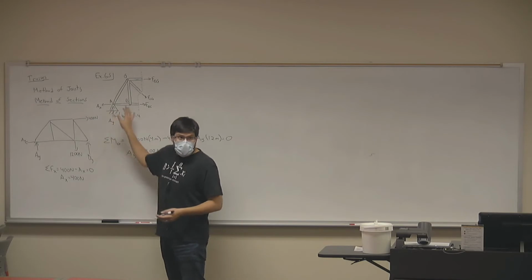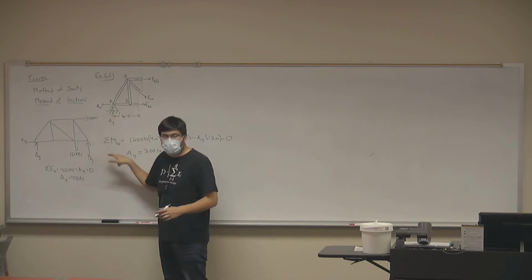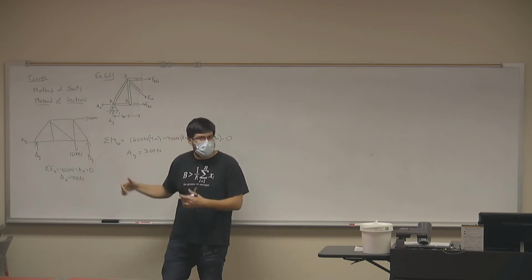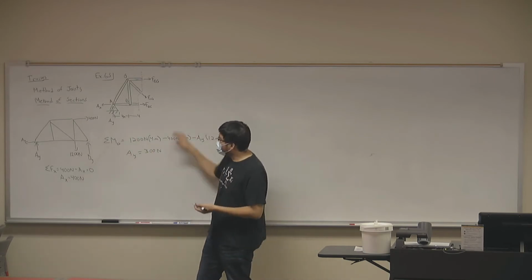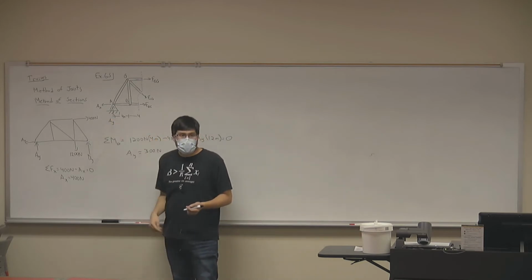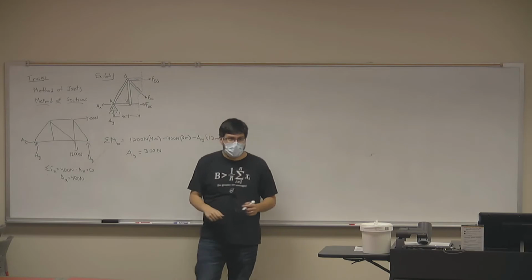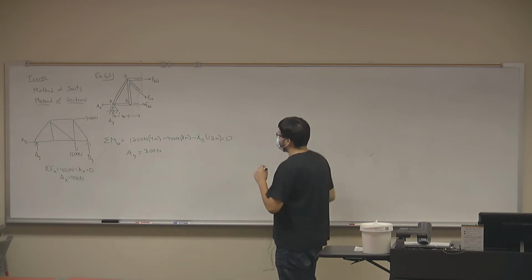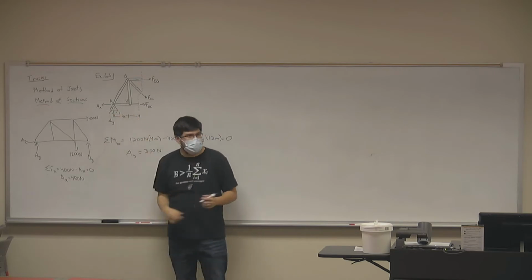When you're cutting your section, remember, if you have any reactions, you want to solve for them first. Okay? Don't do like me. Don't cut it and then realize that you have to draw it out again. So when you cut your system, solve for those reactions first so that you can use them to find these forces. And now my question is, now that I've cut my system, I have my 3 unknowns and I have my 2 reactions, how can I solve this system?